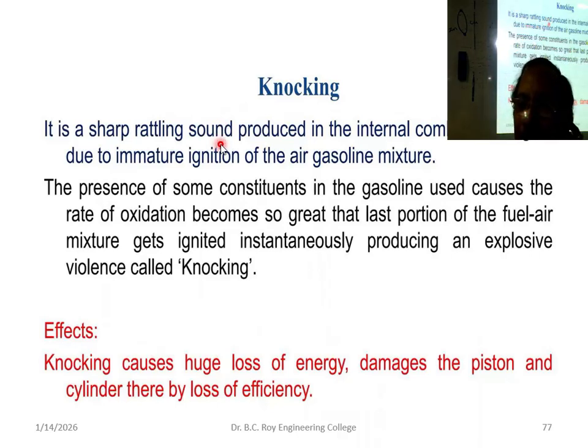The presence of some constituents in the gasoline used causes the rate of oxidation to become so great that the last portion of the fuel air mixture gets ignited instantaneously, producing an explosive violence called knocking.